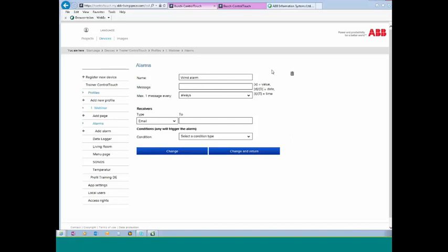And what I can do is to say, okay, an alarm occurred on, and then you can use this one, DTT. You see it in small letters and in large or big letters. For instance, small t is hour and minute. Big T also gives seconds. So it depends on what you want. In this case, I want it to display that an alarm occurred on that day at that time.